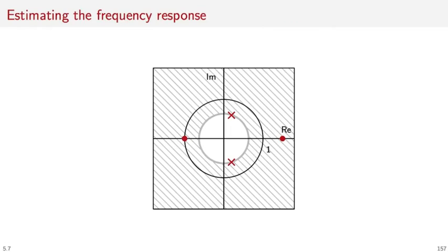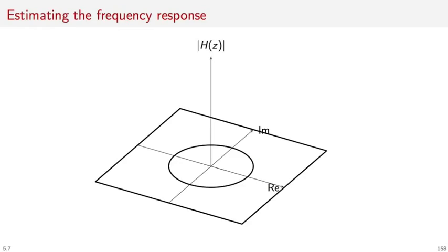Imagine a simple pole zero plot like so, where you have two zeros and two poles. The complex poles are complex conjugate, as is the case for real-valued systems. Let's plot the complex plane in a 3D perspective, where on the vertical axis we will put the magnitude of the z-transform. So we put the zeros and the poles down, and we can indicate the uplifting action of the poles with deltas like so.